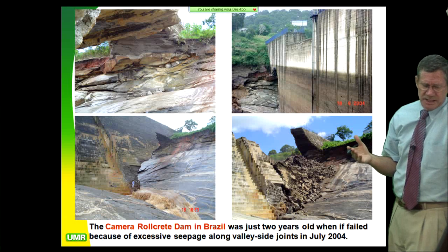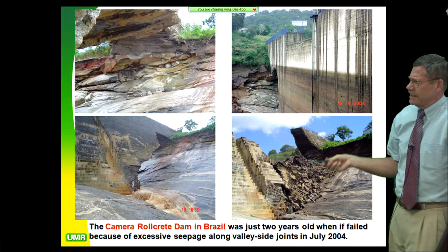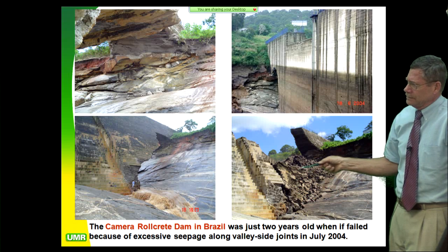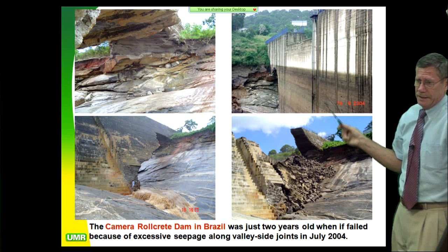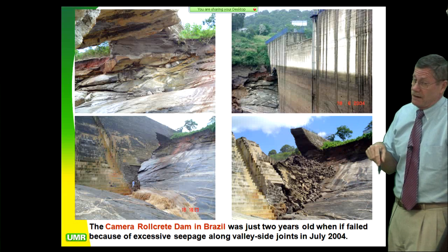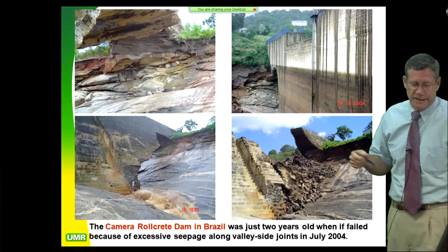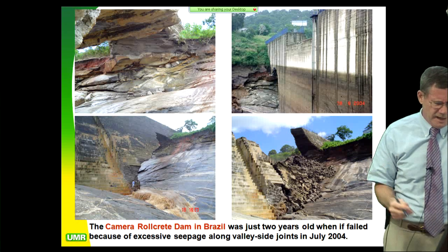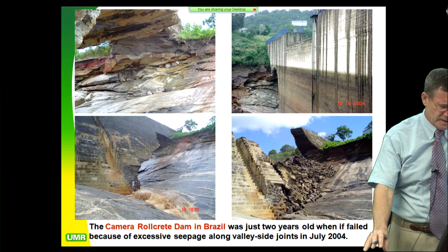That's a dangerous situation. So in this case, they did not do a good job of building a grout curtain up their sloping abutment with uplift relief wells downstream of the grout curtain. That's been a standard detail on all American dams since the late 40s. They chose not to do it there because they thought they had a very good rock material.